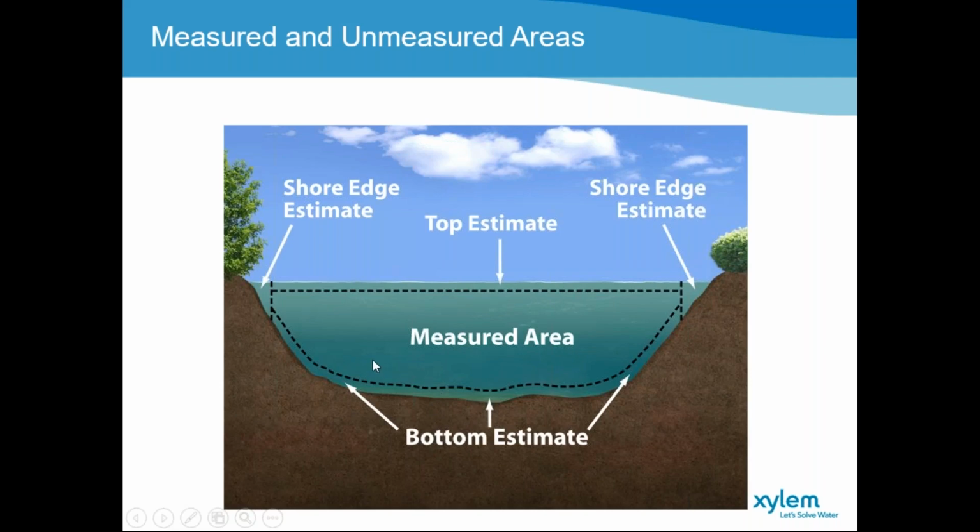The edges are basically limited to the minimum depth the acoustic Doppler instrument can measure in. The international standards requirement for edge measurements is where you are able to collect a depth with 2 valid cells, and then 10 samples or ensembles are measured at that specific location and averaged to extrapolate towards the water edge.